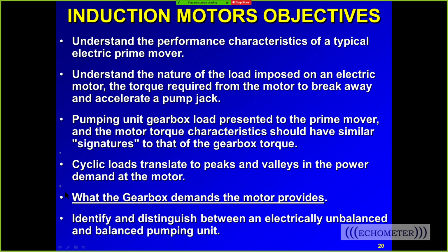And this sentence right here is probably my favorite sentence in this presentation: the gearbox demands and the motor provides. And so there's this relationship. If the gearbox says motor burn up, the motor's going to do what the gearbox says. Unless the motor's protected, it's going to burn up. So they're very much in a symbiotic relationship. I don't know if the motor gets much from the gearbox, but it does exactly what the gearbox needs. And we can easily tell unbalanced versus balanced because the peak on the upstroke or downstroke will be higher on either one if it's not in balance.